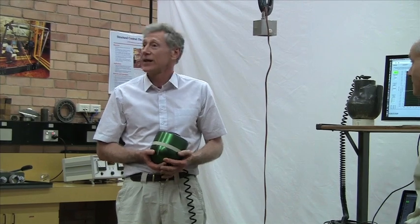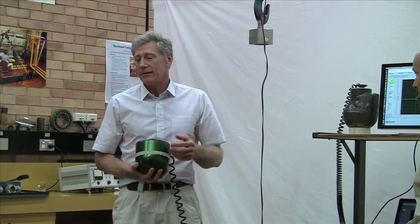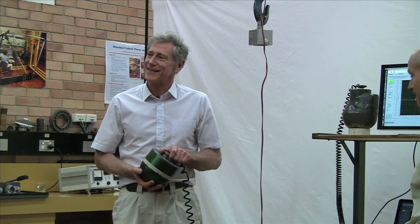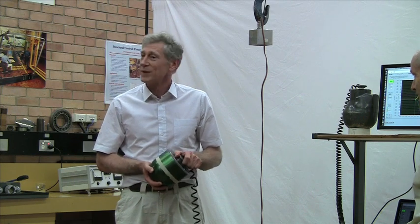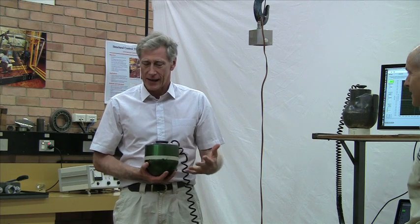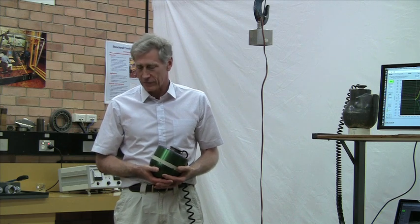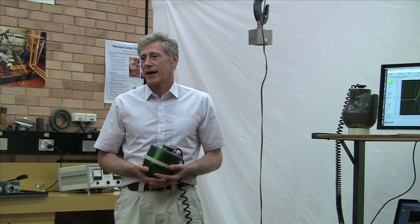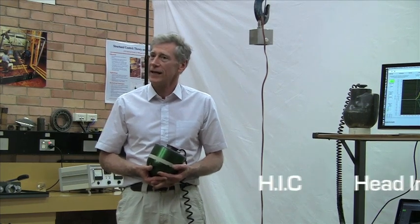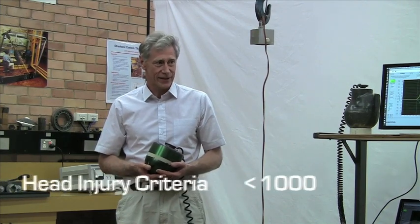You've probably all been to a playground, played in them yourselves, and noticed that there's rubber surfacing, impact attenuating surfacing, there'll be bark, there'll be sand. And you may have wondered, is there an Australian standard for the performance of that surface? Well, yes, there is. AS/NZS 4422 sets out the performance characteristics of playground surfaces. They are pass-fail. We have a 1000 HIC, head injury criteria, and we have a 200 G max criteria.